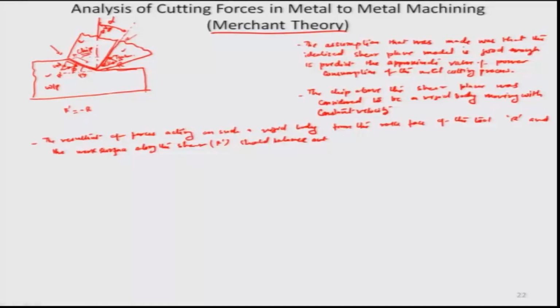Obviously, there would be deformation because the chip was earlier the workpiece which was extended by this dotted line here, which is actually rotated in this direction to formulate what you call this chip. But we are not talking about that instance, we are talking about an instance when this formulation has taken place already and the chip has started to formulate and come out, and there we are trying to do the rigid body assumption. Okay.